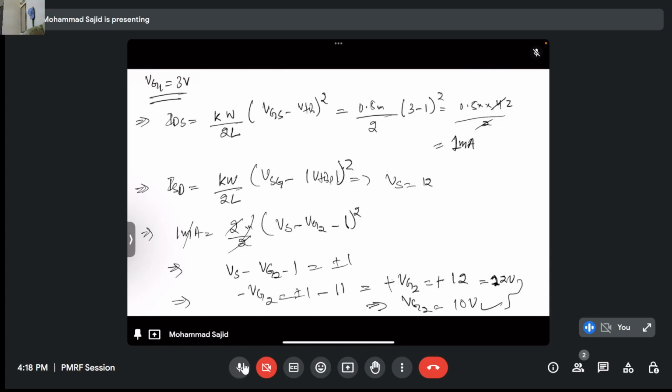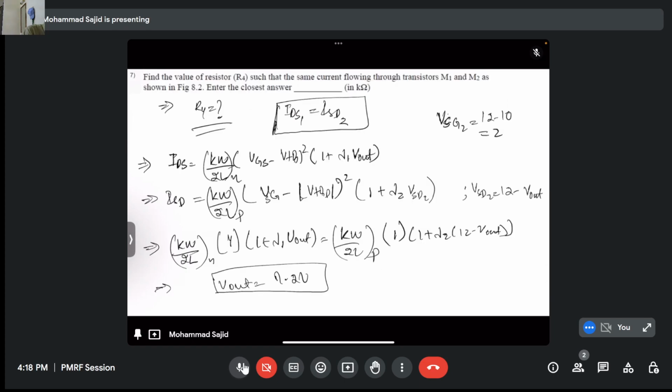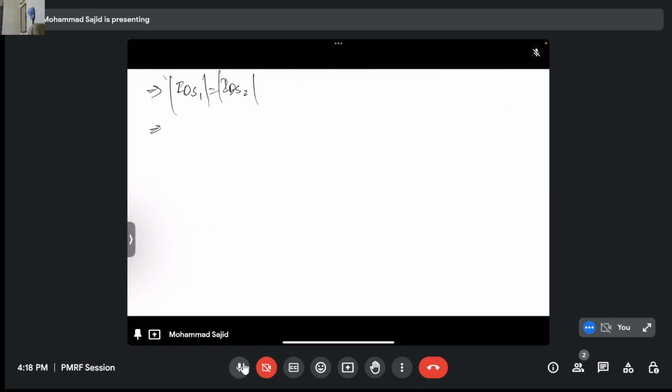So this will involve this IR3 will be equivalent to IR4. So we'll assume a zero current flows through. So this will give me VDD minus VG2 divided by R3 is equivalent to VG2 minus V0 divided by R4, right?